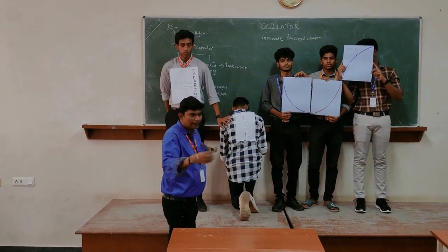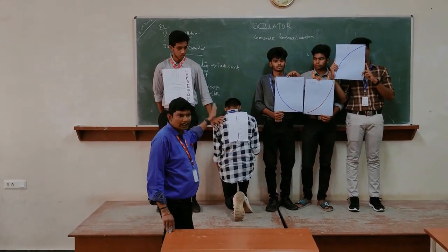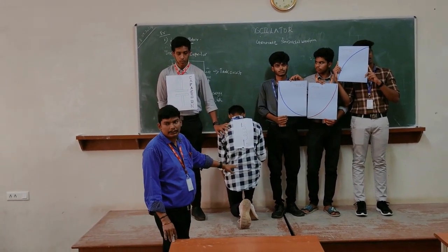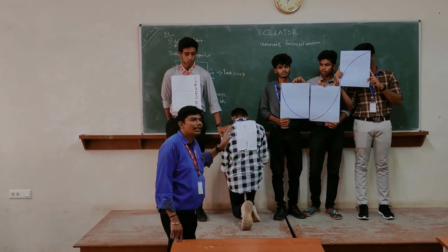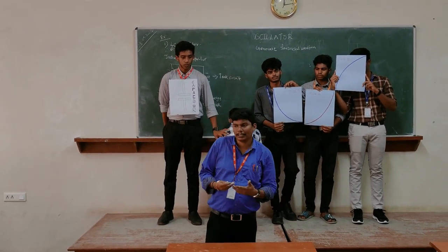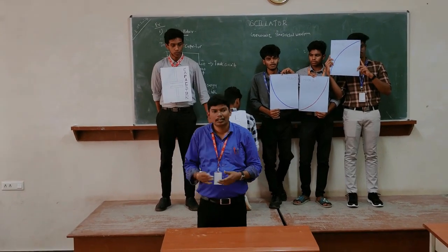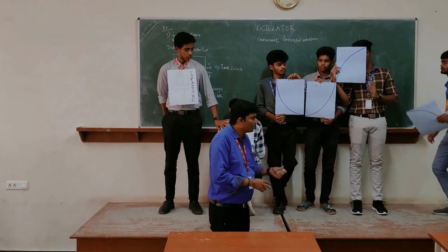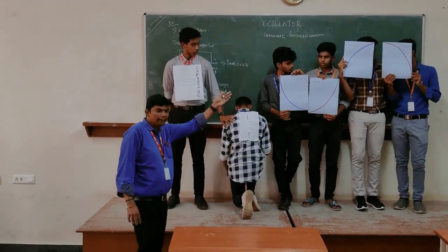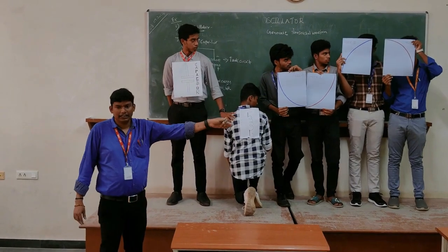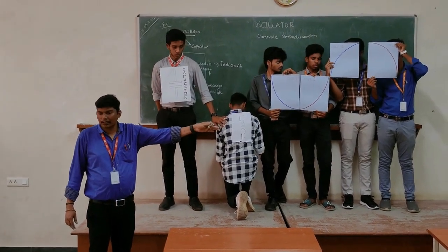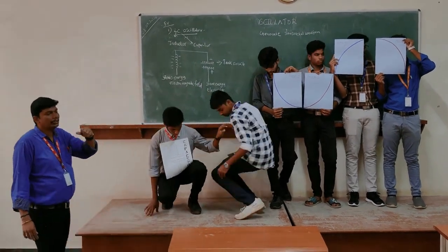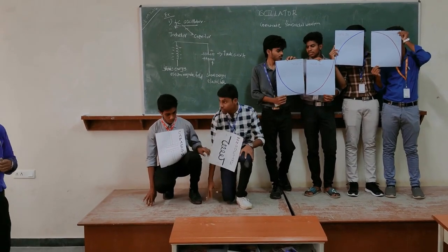Now the repetition. What happens now? When the capacitor gets its full energy, the inductor is flowing, right? So the capacitor is now in the condition of providing supply or charge to the inductor. Mode 4 will again start discharging from C to D. So again, the capacitor is going to discharge and the inductor is going to store energy.